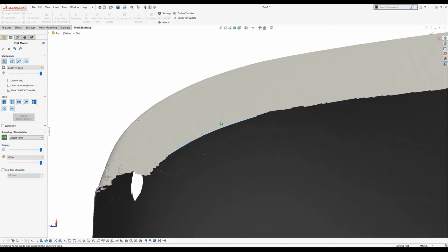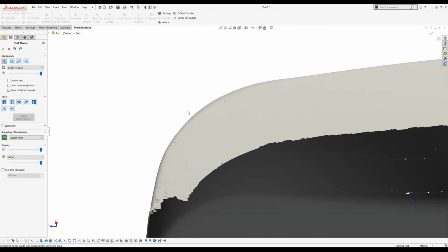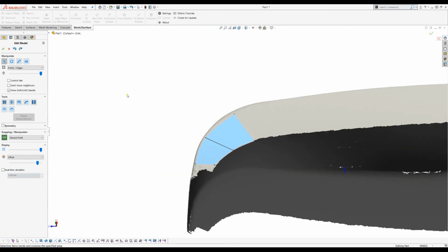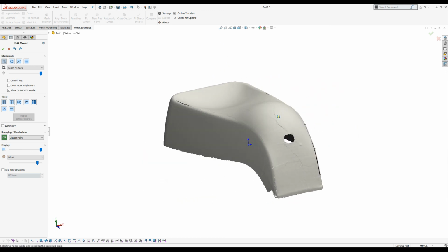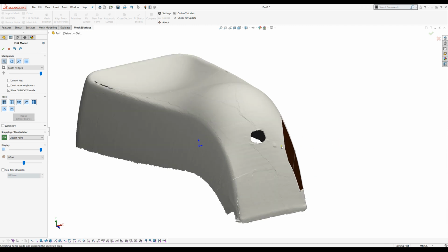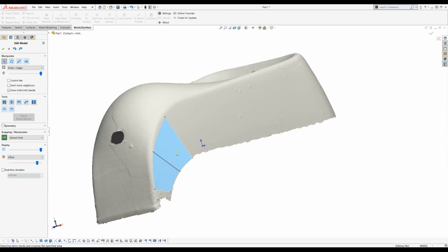which is normal because it doesn't have enough resolution. So technically you don't really see where your surface is. For this reason, we allow the user, only for visualization purposes, to offset the mesh slightly behind my point of view. If I zoom in, as you can see, this mesh is kind of offset. I can play a little bit more. You can see how I adjust this, and the mesh is displayed slightly behind the object. This is quite useful, and so you can adjust your visualization for ease of use.